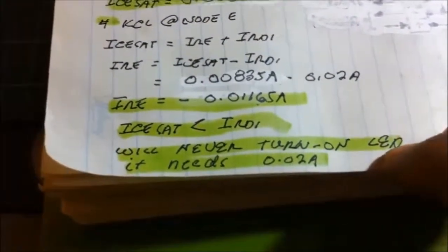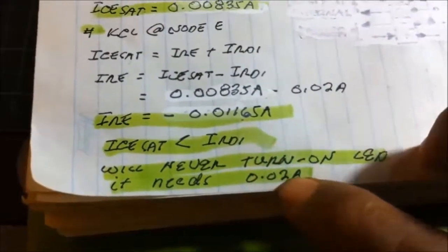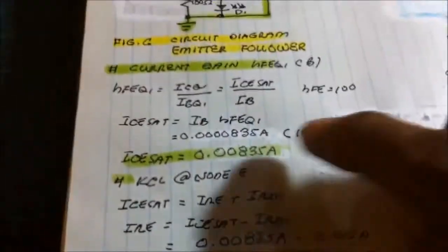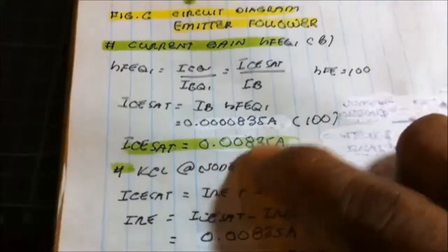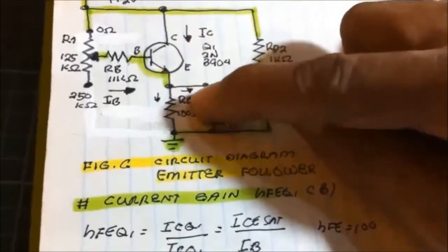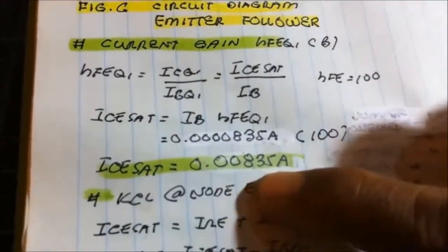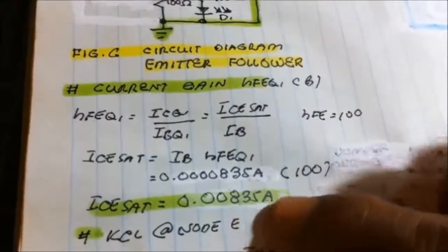So this will never turn on the LED. It needs 0.02 ampere or 20 milliampere. But our supply is 8 milliampere.